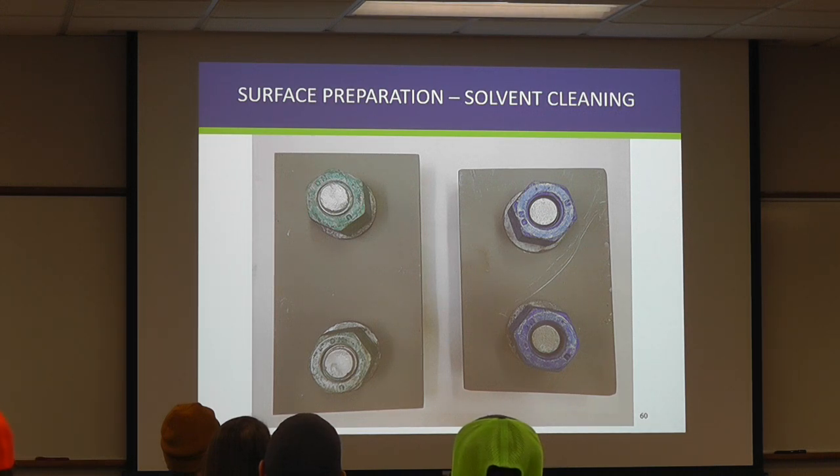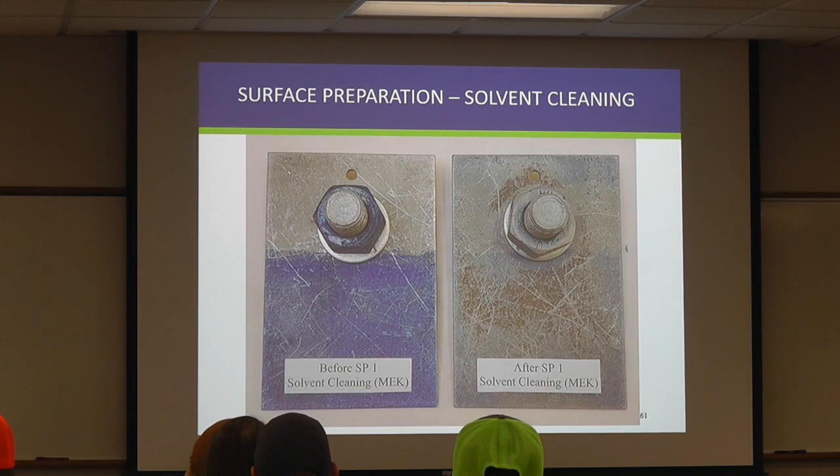So you're not going to want to sandblast every square inch of these things and rip all this galvanizing off and take away your protection. So you can use a solvent. So MEK was used on this. You won't get 110% perfection, but as long as it looks as a visual representation somewhere in this neighborhood, you'll be in good shape because your primers will bond.